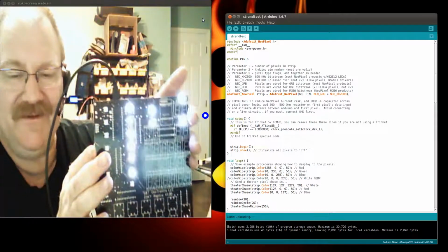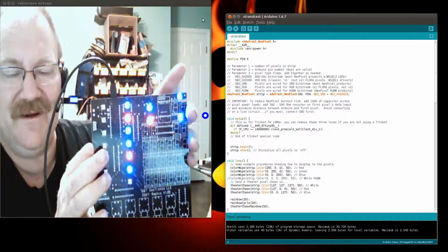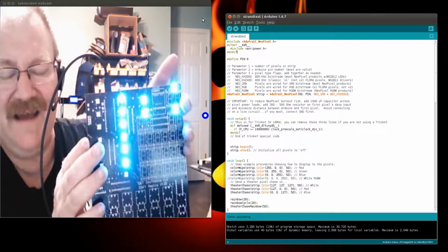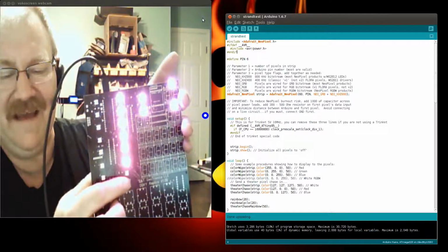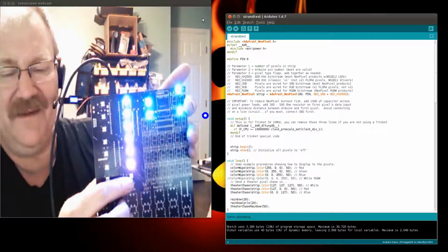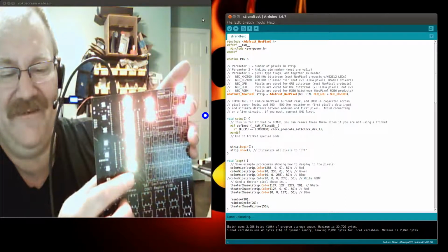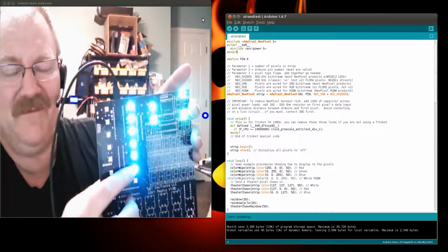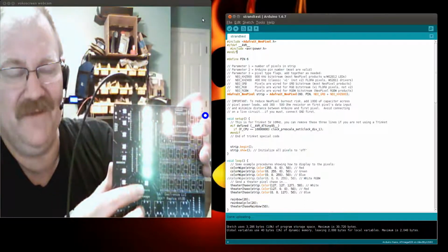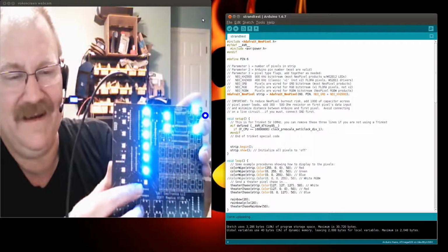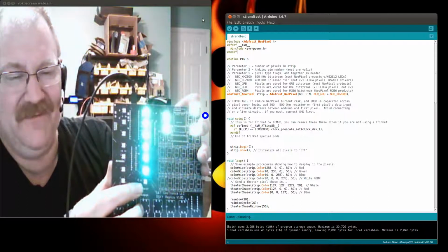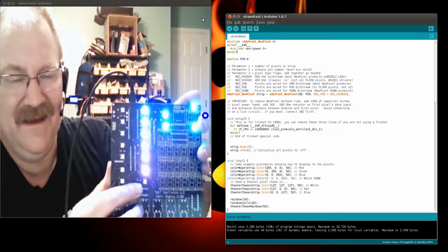In troubleshooting this, you'll understand that all of them are working just fine, from 0 to number 9, and number 10 isn't working. The problem is more than likely either number 10 itself or a problem with number 9, because the signal goes from one to the other. Each one thinks that it's device 1, and basically they subtract 1 from the total packet that's going around and pass it to the next one.